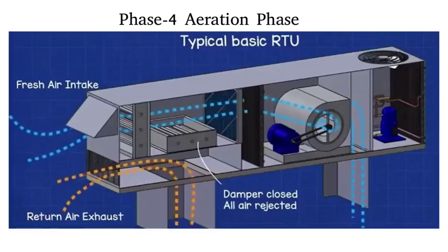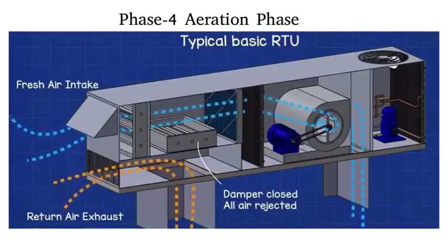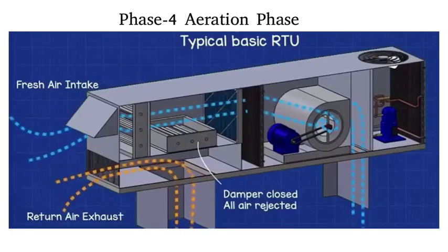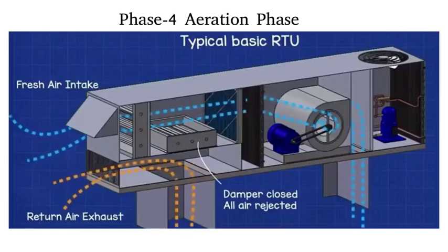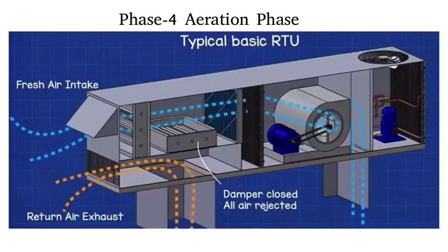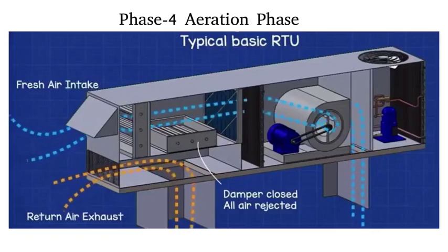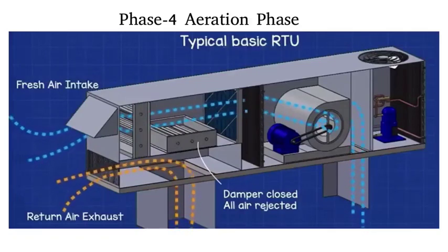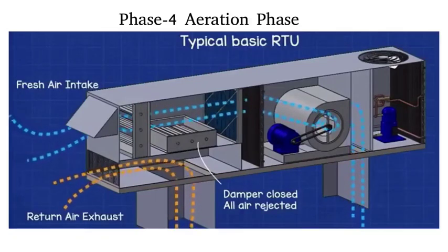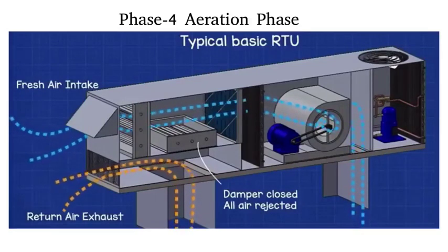Aeration phase is the last phase, where H2O2 is flushed out from all isolator surfaces, including filters, by the air handling unit in once through mode. The time depends on both the air exchange rate and H2O2 desorption from the decontaminated material. The final H2O2 concentration is accepted below 1 ppm as per